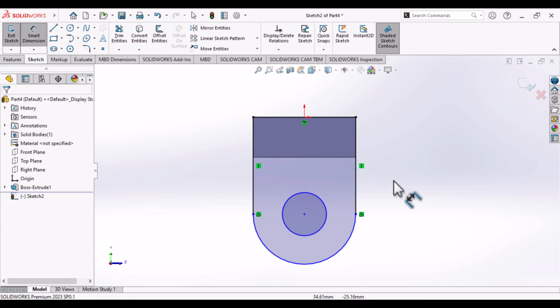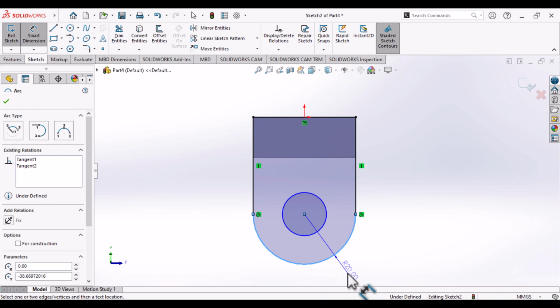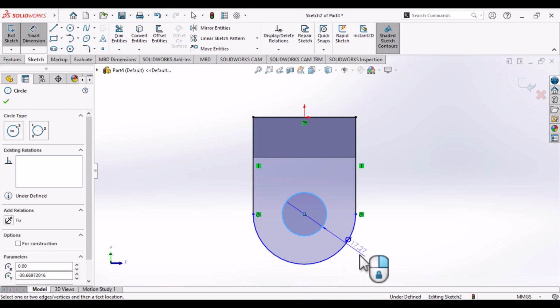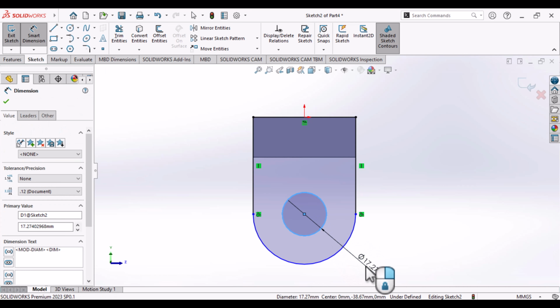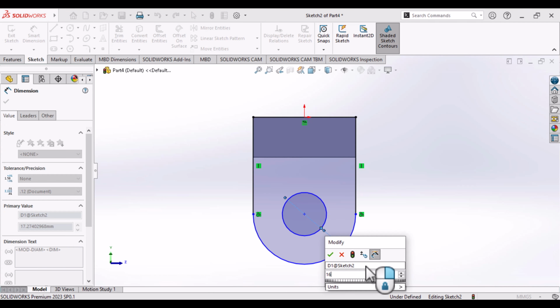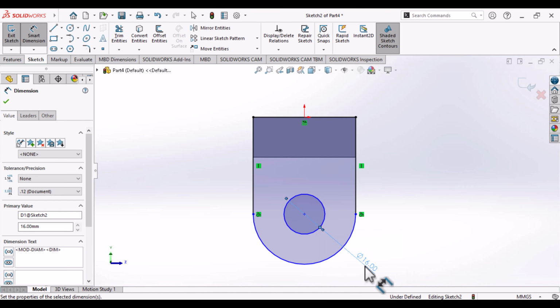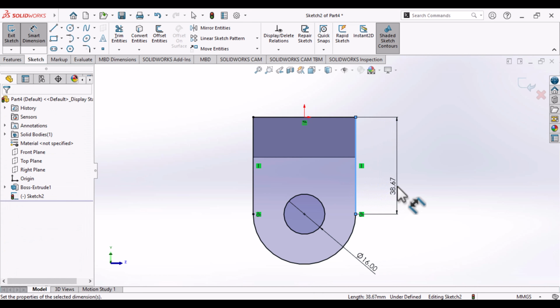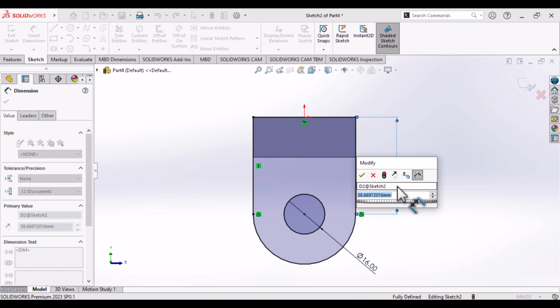Let's go to Smart Dimensions. This is already constrained using this length. So the radius is already 20. If you need to confirm, you can click. You can see it's 20. Escape. So we're going to define the inner one. And the diameter is 16, once again. And then this length is 60 minus 20, 40.